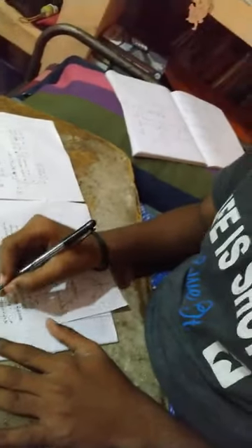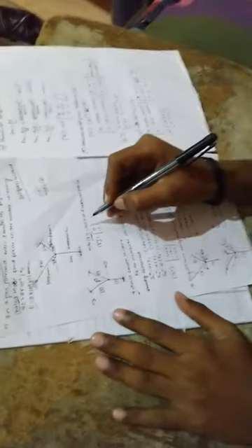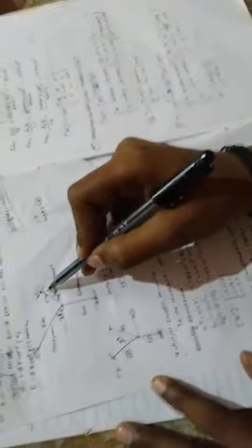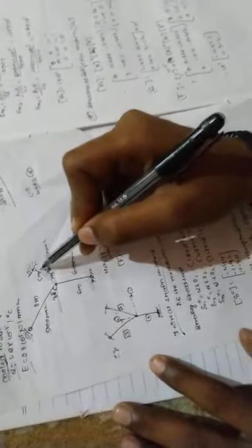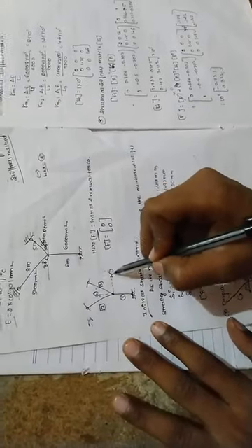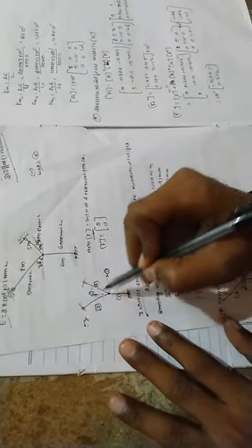So in this temperature change problem, we have different steps. In the first step, we have to consider the initial or the external forces. You have to first find out the external forces. In this truss, there will be no external forces, so the external force matrix becomes 0. So we consider two members, the horizontal one and the vertical one.